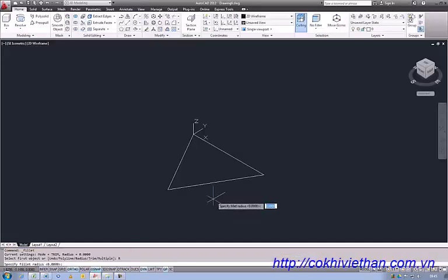So back to AutoCAD, and let's type in 0.28868 and then hit enter. Right, now to select our objects. So we'll select near the apex one line, select the other line, and there we have our fillet applied.